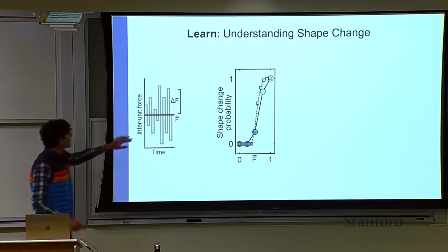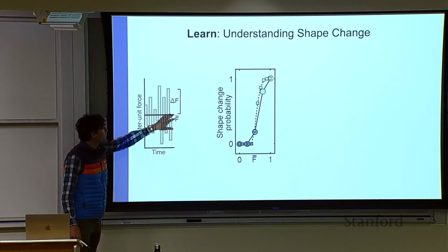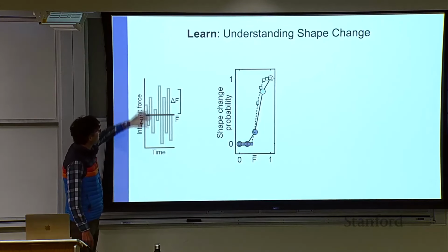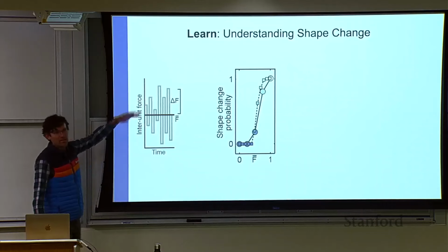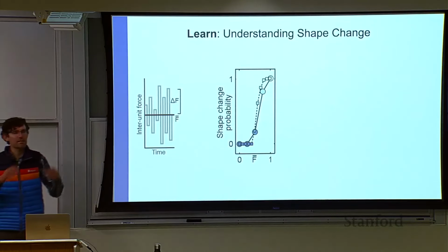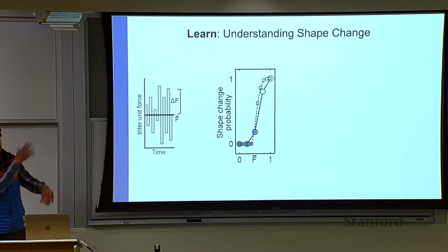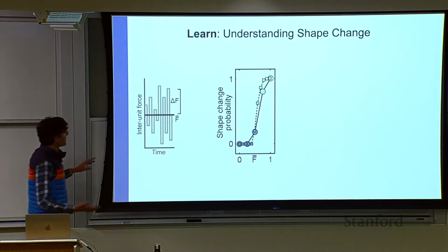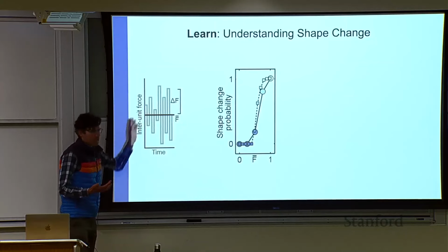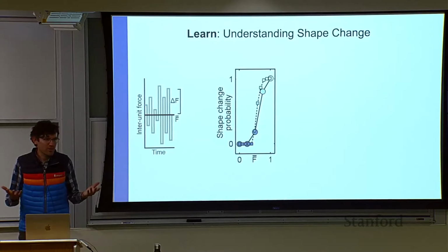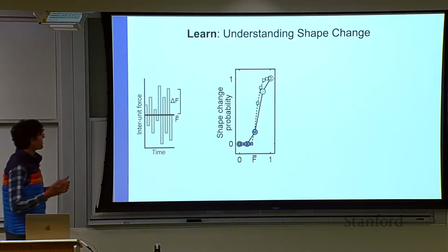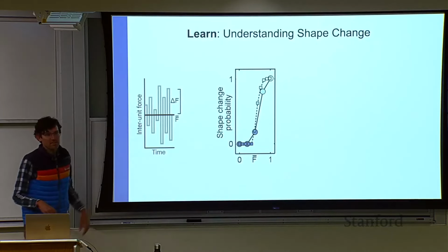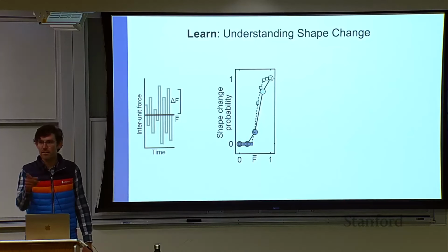Even though our average force, so let's say this is case 1 with no fluctuation, here's our average force. Let's say our critical breaking force is here. Then by fluctuating about this, I'm going to get over that threshold, and then it's going to crack, and then go, and then it's basically an energy flow. It's a downhill slope after that. So it just needs to get itself over that. If force requires some energy or some power, it's more favorable, and I'll talk about power in a minute, to kick hard and then take a rest. Kick hard, take a rest. Yeah, great question.